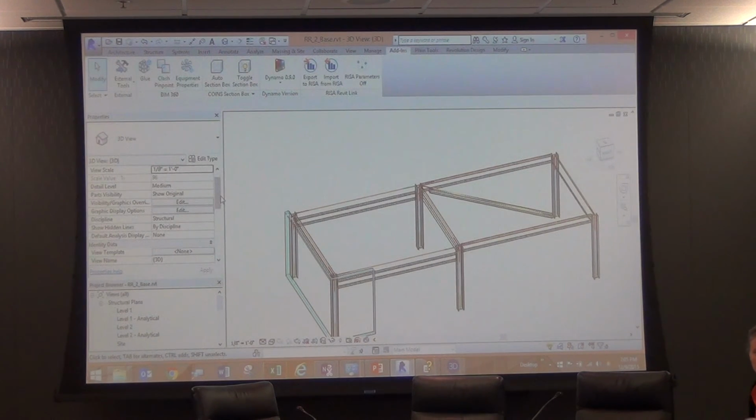I can see if you like it, you can try it, but essentially what it does, so one of the things with sloped roofs, I don't know what you've normally done, but there's a deal where you can say, I want it to lock to the underside of a floor system. So you slope the floor, and then all your stuff you model is actually locked to the underside of that floor.